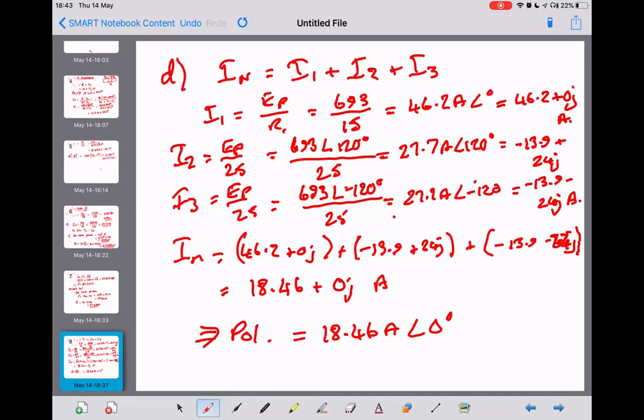And then all I've done was write, we know each phase angle is 120 degrees apart, and then I've gone IN, again, and just wrote them down. As long as you get the right answer, the method is immaterial. I didn't go through and work out I2 and I3 again. I just put the angle on the end, and that's fine because you're using your knowledge that the angle's going to stay the same.